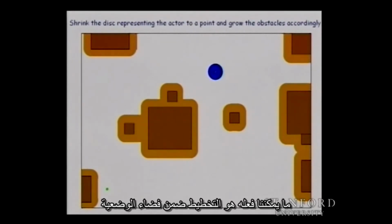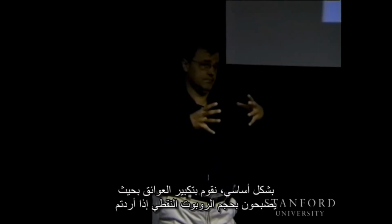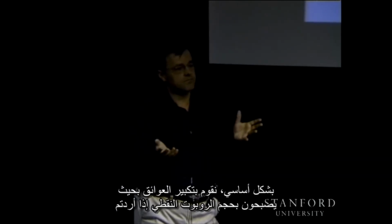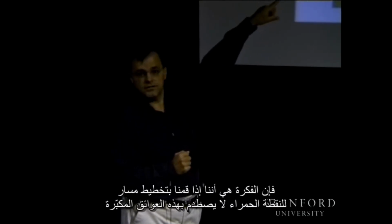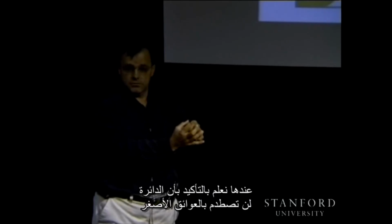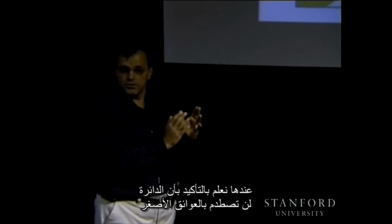So what we can do is plan in configuration space. Basically, we take the obstacles and we grow them by the size of the point robot. If you look at the red dot there, the idea is that if we plan a path for the red dot that doesn't collide with these grown obstacles, then we know for sure that the circle is not going to collide with the smaller target obstacles.